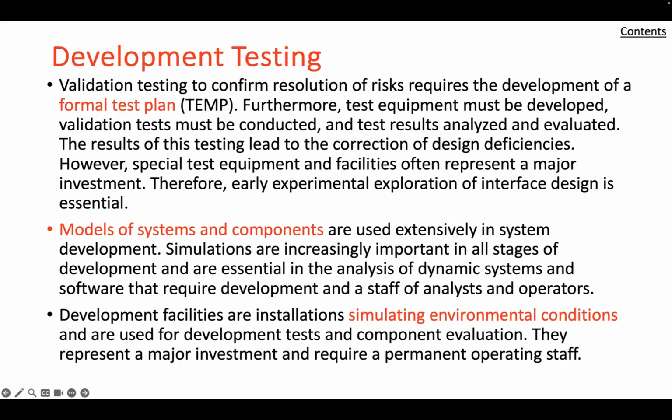Three, determine the conditions under which these parameters will be tested. Four, review the process leading to the selection of components requiring development and the design issues involved in the selection. Five, review the development test results and the degree of resolution of design issues. Six, identify all interfaces and interactions between the selected components and other parts of the system. And seven, on the basis of the above, define the appropriate test configuration that will provide the proper system context for testing.